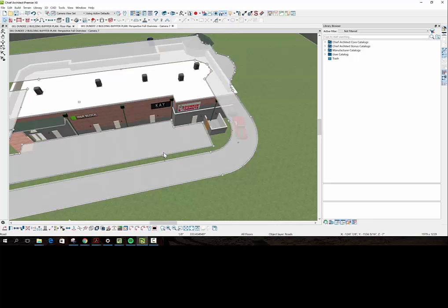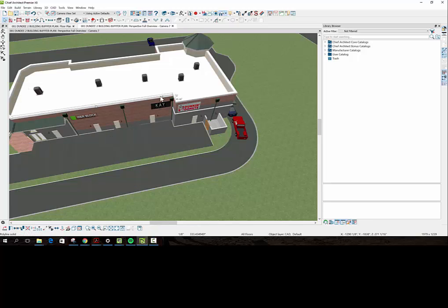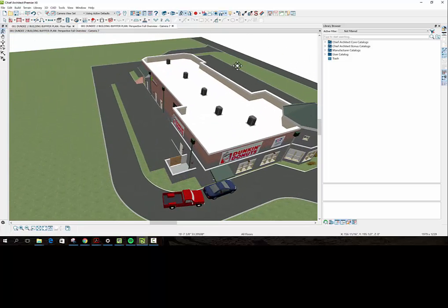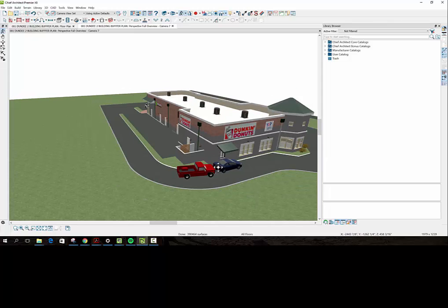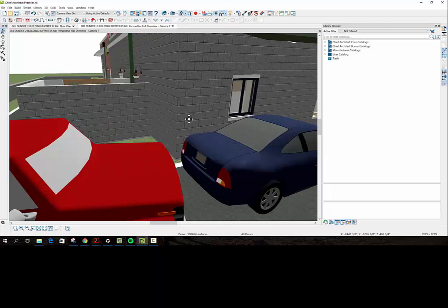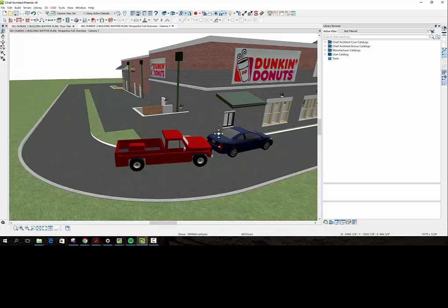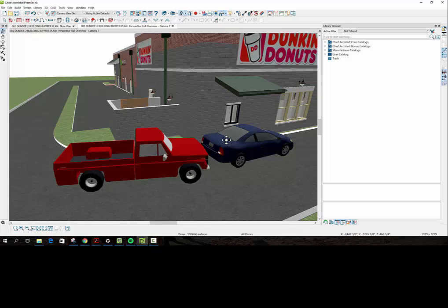All right. There's our curb and gutter. And there's our scupper box coming down there, but we just discovered that our high point, it makes no sense to try to drain it to this. We want to be down here somewhere. So what does that look like when we go around the building? We're going to have a downspout right here, right where people are congregating. I'm not that happy about it, because you can pull up the drive-through window and say, "Do you mind if I tear off your downspout while I get my coffee?"